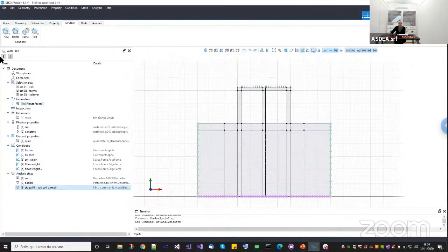Okay, so basically, what does STKO do? If you do not specify in the entire model stages no model subset, STKO will use the default behavior. So it will put all the elements since from the very beginning. But if you specify at least one model subset, then all the other pieces will be added only if you use other model subset, okay? So once you use the model subset, the construction of the model should be done explicitly.